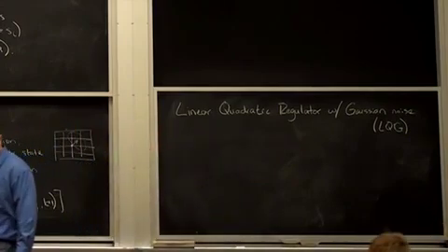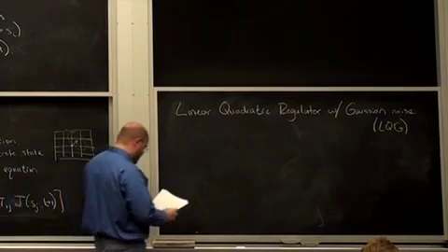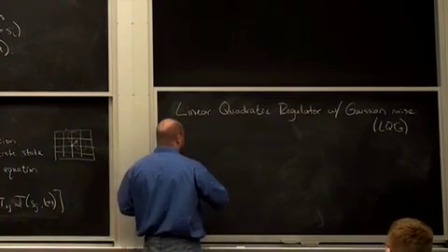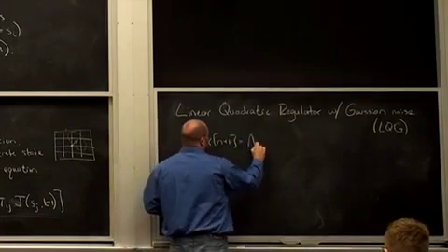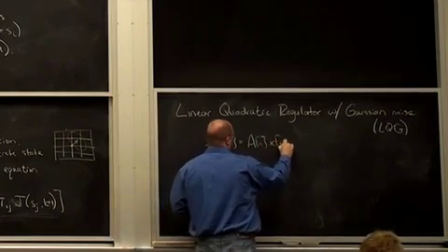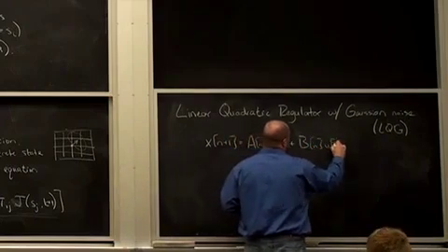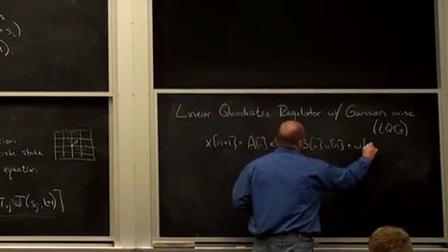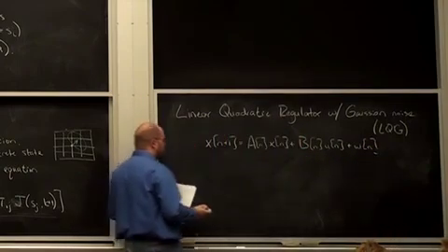There's two forms of it. One of them is Gaussian noise also on the sensors. But let's just worry about the case where we know there's no uncertainty in the sensors, only the dynamic noise. So x[n+1] is A[n] x[n] plus B[n] u[n] plus w[n]. It could be time varying or not. The cost function again is the quadratic regulator.